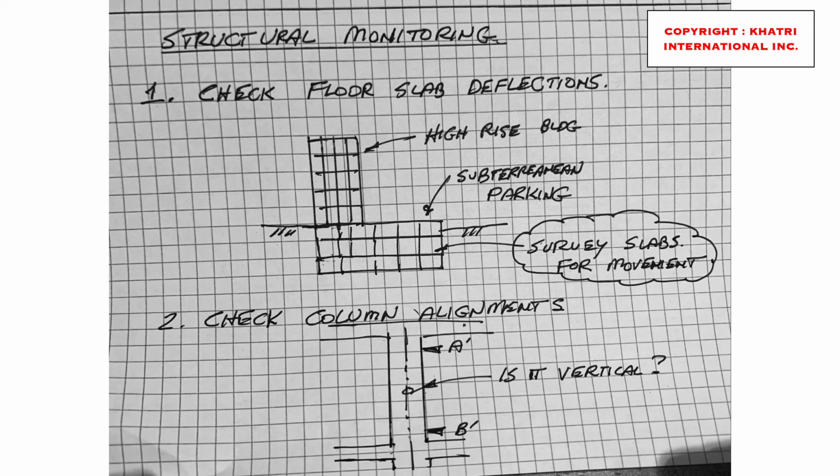And this is the area where I think we as structural engineers should be looking when we're called in to look at a building. How do we know whether or not that building is potentially in a collapse mode, may have already started to collapse and we haven't noticed it? This is an analytical procedure that we can do in the field to measure and see whether or not that building is moving. And I highly advise that we do this as part of our scope.